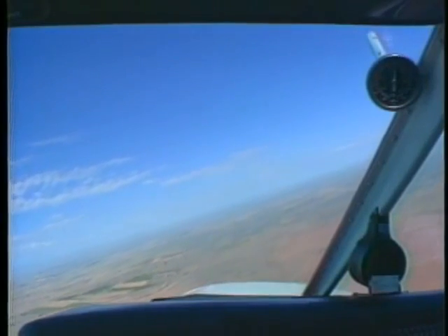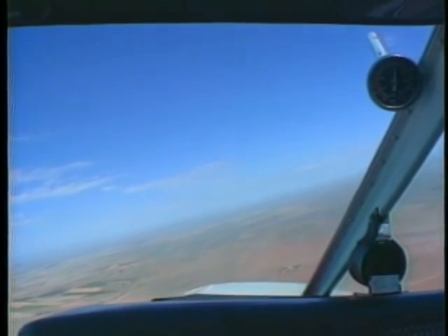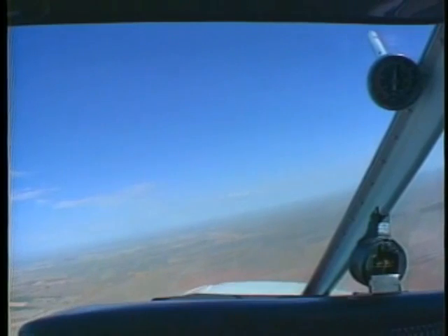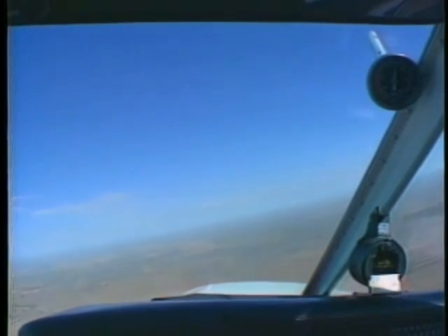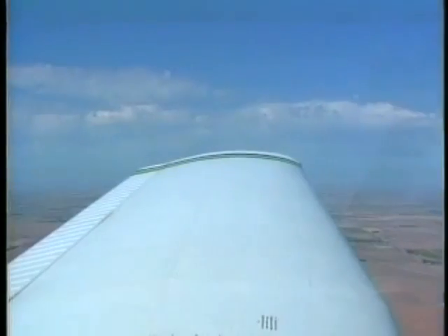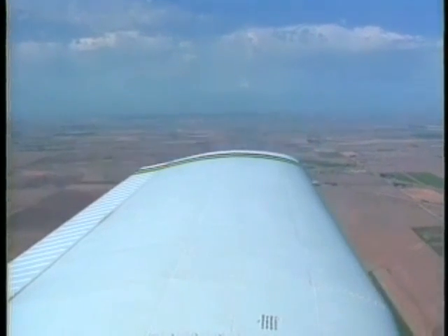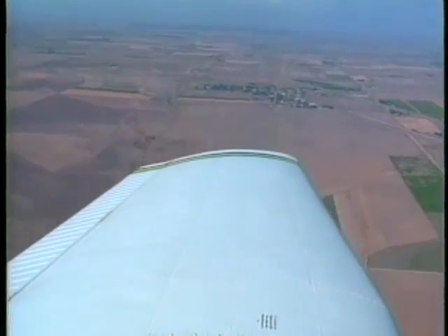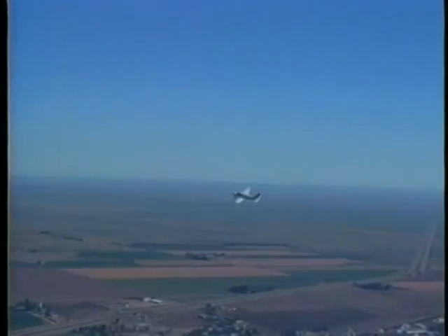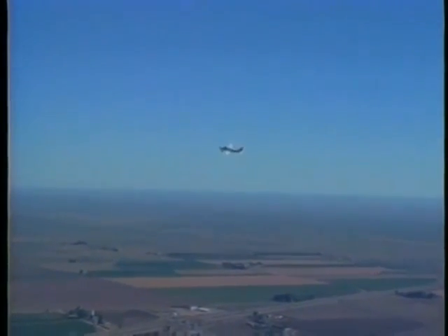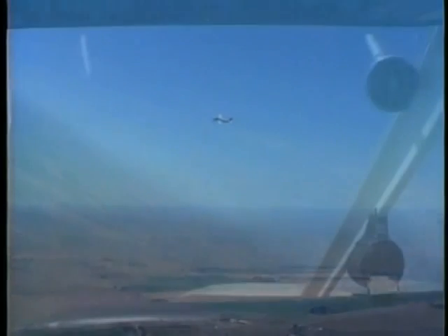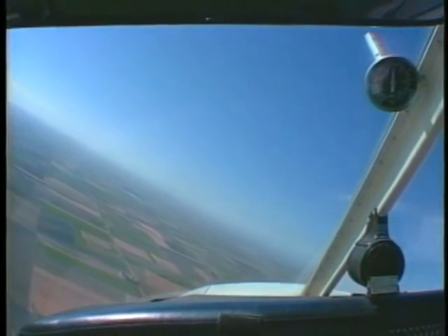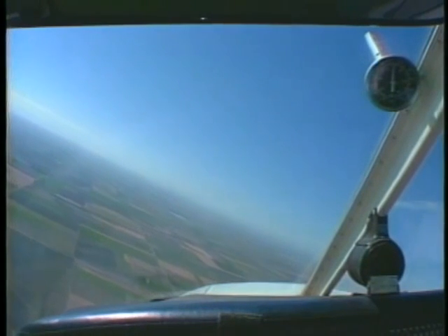As the airspeed continues to increase, maintain coordinated flight and time your rate of rollout and pitch change so you reach straight and level flight at the 180-degree point. This should be abeam the 90-degree reference point at your entry altitude and airspeed. Immediately enter a climbing turn in the opposite direction. Complete each 45-degree segment in the same manner as it was performed during the first half of the maneuver.